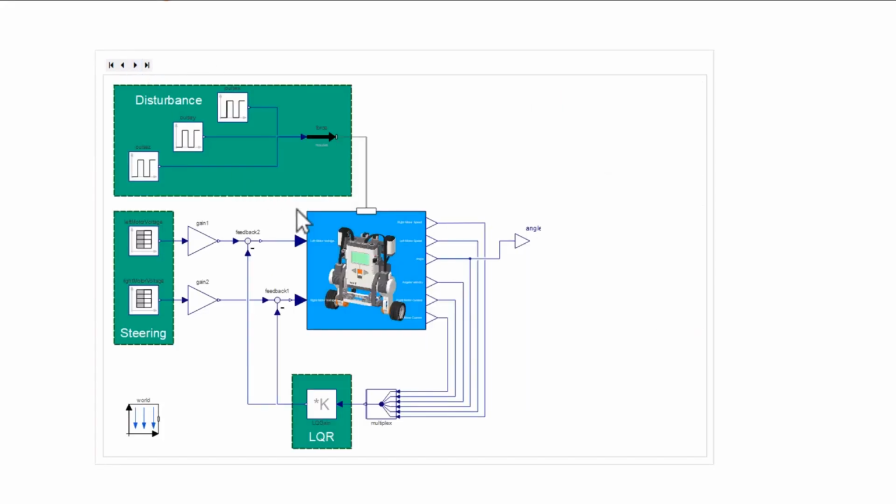Sometimes the objective of a model is to come up with the simplest model possible. For example, let's say you want to use a feed-forward controller that you want to deploy on real-world hardware. These controllers use a model of the system to operate. If you use a very detailed model for such controllers, then your controller might be computationally expensive and needs more time to respond to change. This, in certain cases, will make the controller unusable as these controllers are expected to respond at very high speeds.